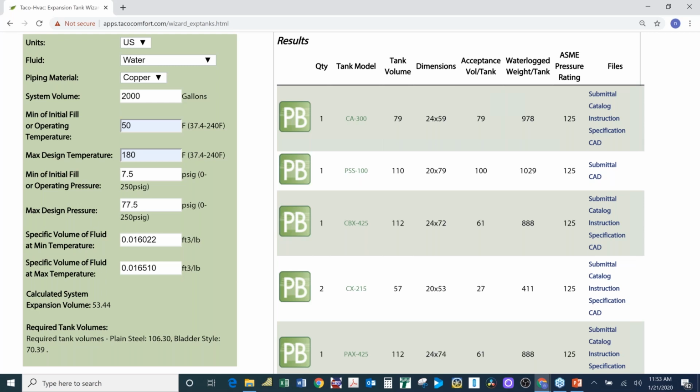Keep in mind that if you do not have an expansion tank, as the fluid begins to expand, one interesting characteristic about water, it's called an incompressible fluid. You only have to change the temperature a few degrees. It will break whatever container the water is in. So when it comes to a hydronic system, the weakest part of the system will break first, and usually that's things like air handling unit coils or boilers or something else. Pressure ratings on piping is usually higher than the pressure rating of the equipment in it, so usually there'll be a catastrophic failure of a piece of equipment if there's no expansion tank in the system.